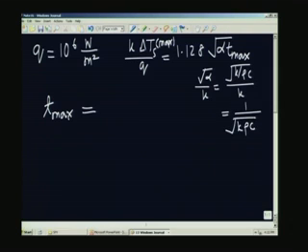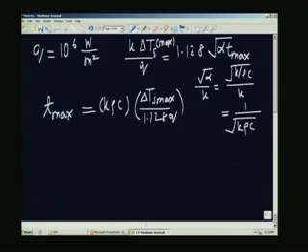That is the reason why in the table we gave the product of these three quantities. So, all I will do is I will just say that t max is equal to K rho c multiplied by delta T s max divided by 1.128 Q, whole squared.